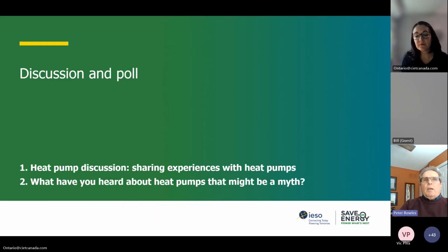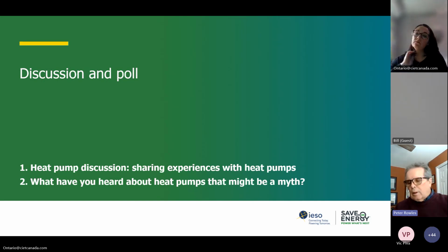Okay, so what's happening during the heating season is that the outside coil is in cooling mode, and once you get below freezing, you are getting into a situation where moisture can condense on the outside coil when it's cooling, and that affects the heat transfer capability of the outside coil. So they do have to heat the coil for a period of time to get rid of the ice on the coil so that they can maintain optimum heat transfer performance of that coil. Thank you.